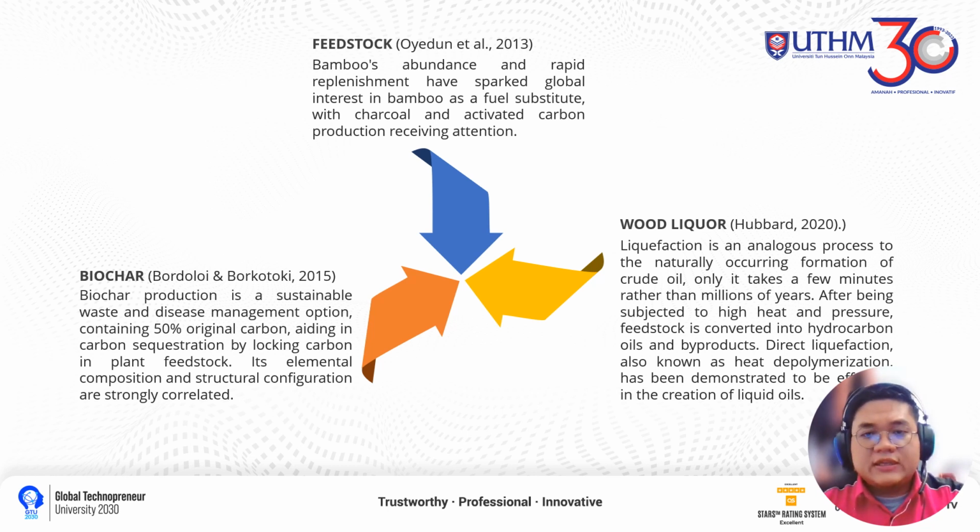And then finally, the wood liquor, as stated by Hubbard 2020, liquefaction is an analogous process to the naturally occurring formation of crude oil, which takes just a few minutes using the pyrolysis process instead of thousands and millions of years when naturally produced. After being subjected to high heat and pressure, the feedstock is converted into hydrocarbon oils and byproducts. Direct liquefaction, also known as heat depolymerization, has been demonstrated to be effective in the creation of liquid oils or wood liquor.